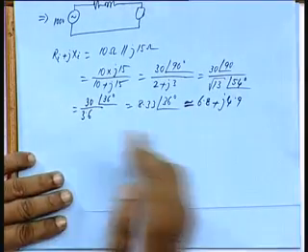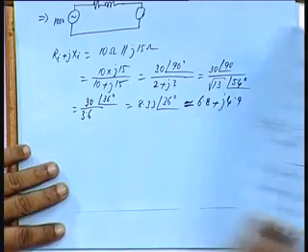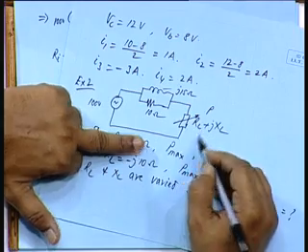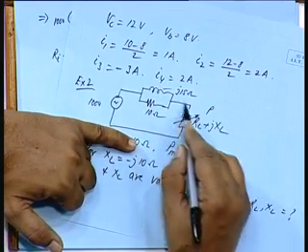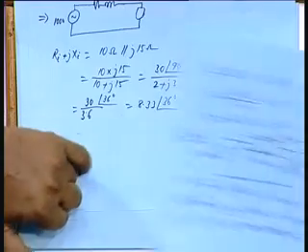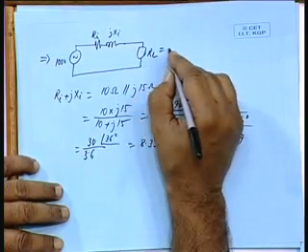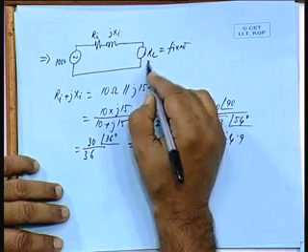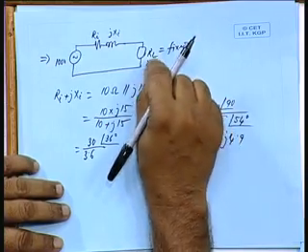For the maximum power condition, when you do not have any scope to change the resistance, I will try to maximize the current. RL is fixed, and I am having only XL which can be varied. So, what should be the value of XL?